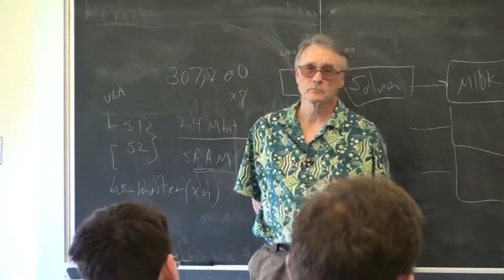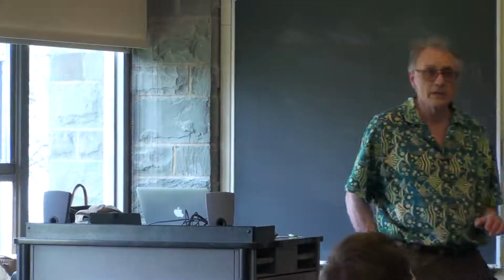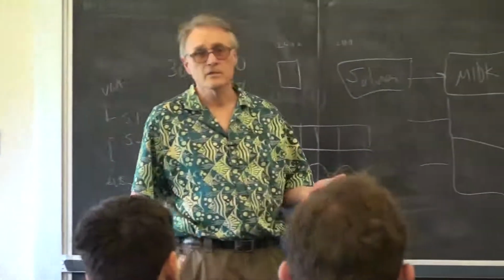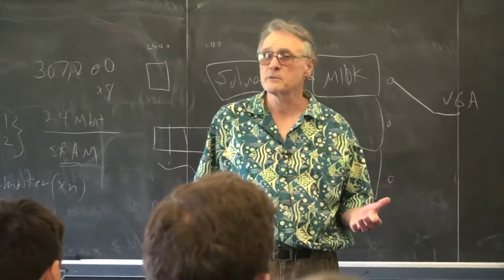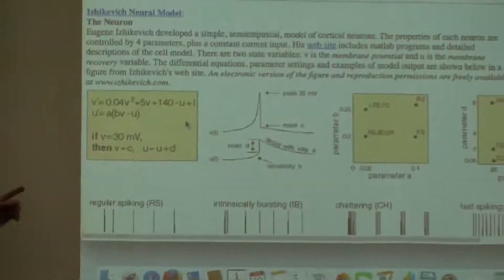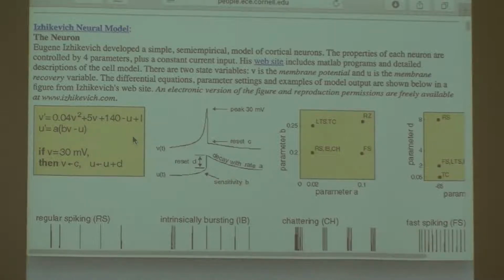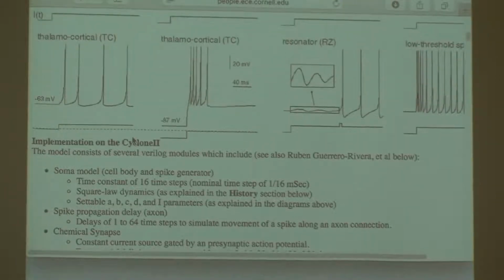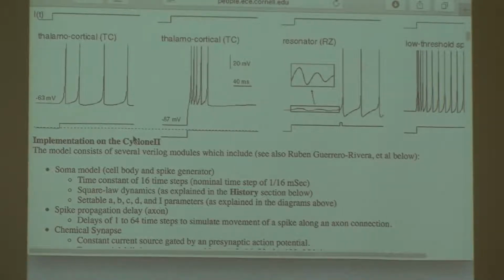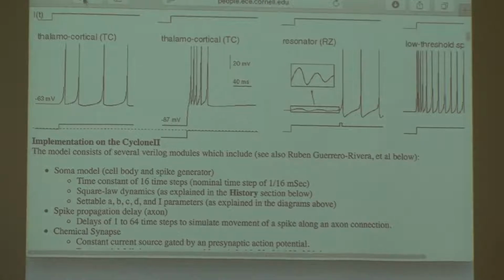What else? I played around a little bit with neural models on the FPGA. My interest was in spiking neural nets as opposed to convolutional neural nets or graded neural nets. So these tend to be time-based systems rather than amplitude-based systems. The amplitudes don't matter, they're fixed spikes just like in your nervous system. What matters is the timing of the events. And so I tried to come up with the simplest system I could that gives reasonable shaped events and allows for learning. I could talk much more about that.